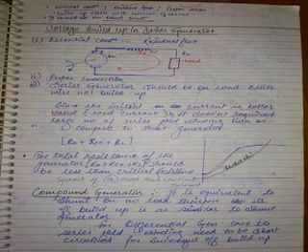If the load is not connected across the terminals, the machine won't build up any voltage. The best condition for a shunt generator to build up voltage is that it should be on no load, and that's the worst condition for a series generator. Yes or no?